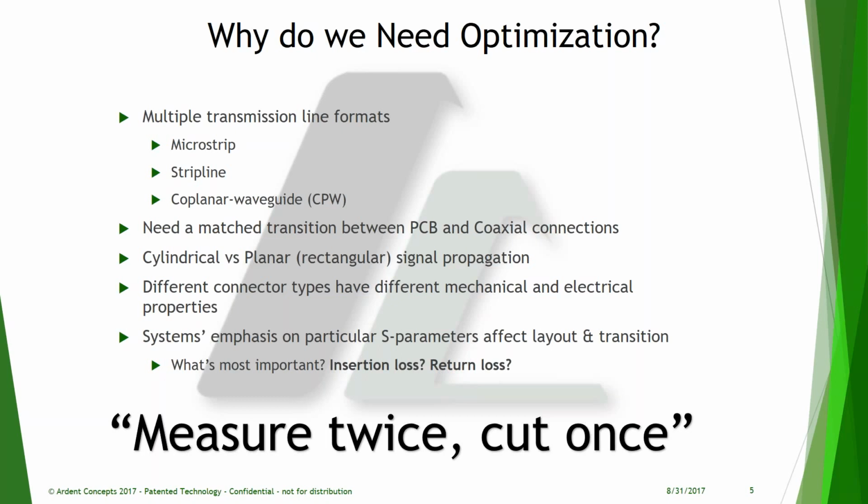Insertion loss, return loss, TDR, and this is what optimization allows us to tune. So that's a tie-in to this quote we have here, measure twice, cut once. This adage comes from carpentry, and it rings especially true in board and system design. The idea that it's easier to get it right the first time is essential.